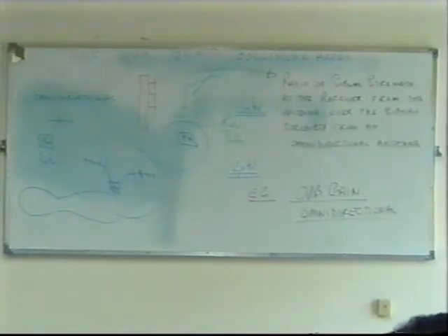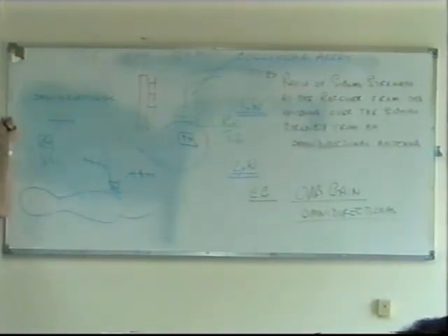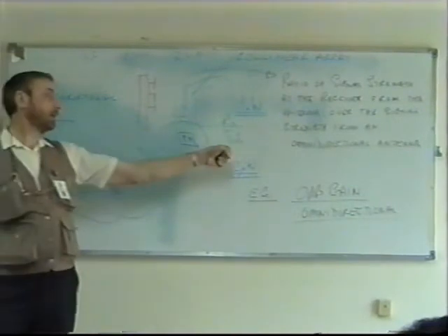It doesn't matter what your system is. If you double the power of your transmitter, forget about what type of antenna you use, what will happen to the power at the receiver? Double. 3 dB, exactly. A 3 dB change at the transmitter gives you a 3 dB change.